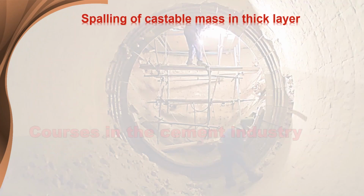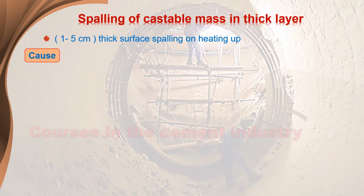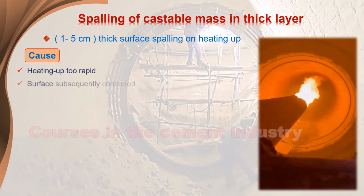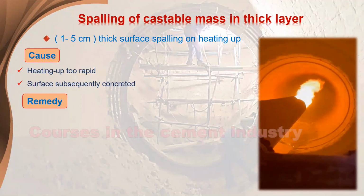Spalling of castable mass in thick layer. 1 to 5 cm thick surface spalling on heating up. Cause: 1. Heating up too rapid. 2. Surface subsequently concreted. Remedy: 1.